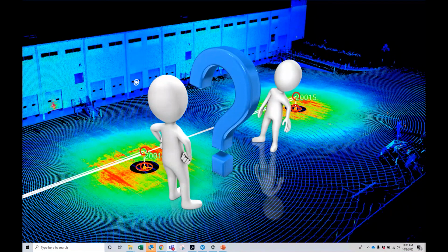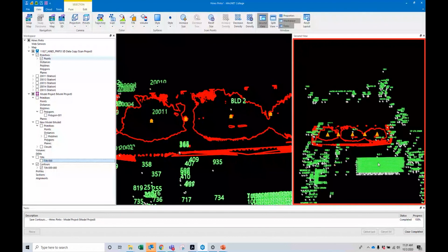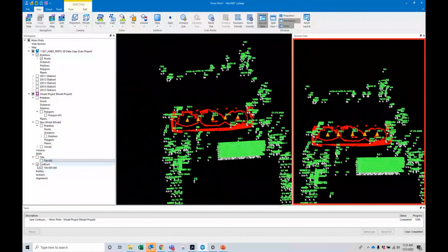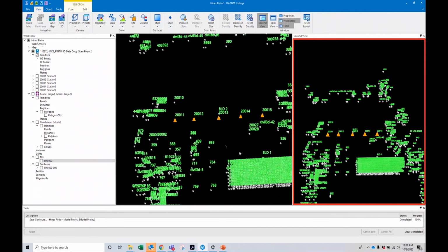Basically put your prism pole at the far end and just work your way to your prism pole. So they put that baseline in based on the two building corners. Yes, sir. Gotcha. Because we'll go back in. Let's turn the points on. If you guys can see all the little tiny points, they had several points to work from.